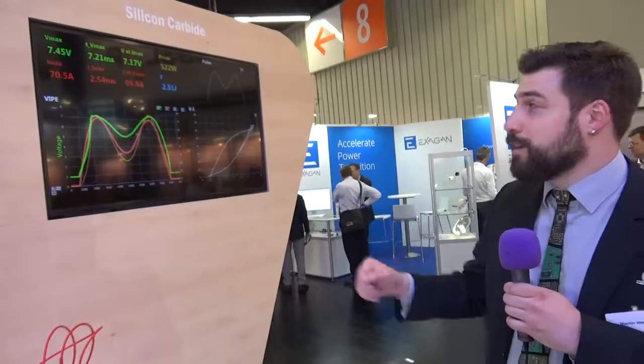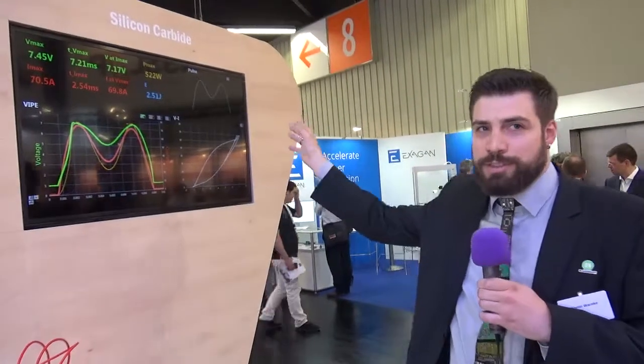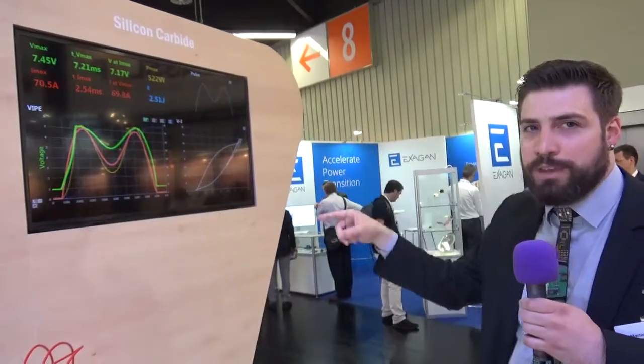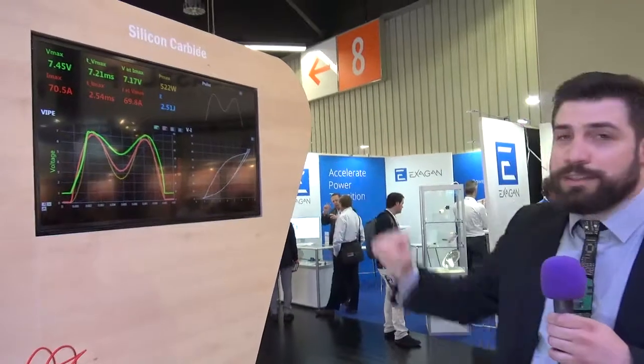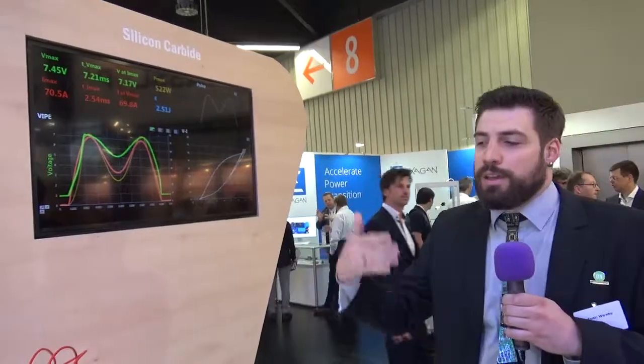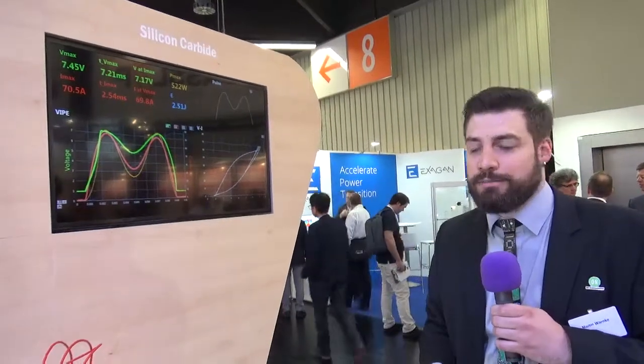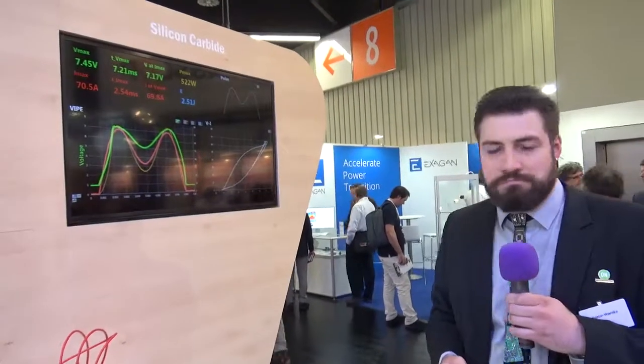What we can also offer to our customers is the possibility to enter custom waveforms here. If a customer has a problem with a 30 amp peak which has a certain shape and asks if the diode is actually able to withstand this peak repetitively or over temperature, we can recreate this pulse in the setup, do repetitive tests even over temperature to actually give reliable data about the device ruggedness. So that concludes this presentation from my side.